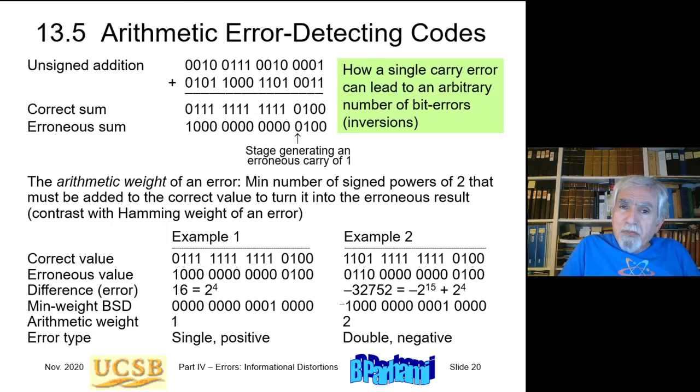In transmission, when you transmit a word over a communication line, and if you have a single bit error, it changes 1 bit, and therefore a single error detecting code, or later we will see also single error correcting code, can deal with that single bit error.